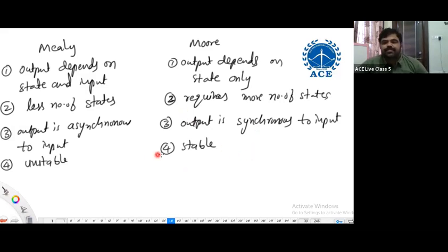What is happening here? Output is affected by input at the next clock edge occurrence. What is on X is captured at the clock edge only. It is not capturing whatever is on X during the cycle. Thank you for understanding. These are the Moore systems.